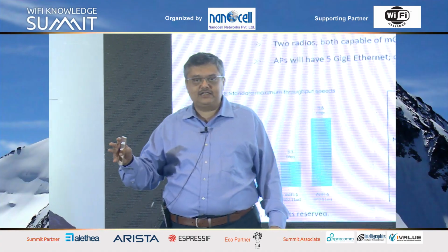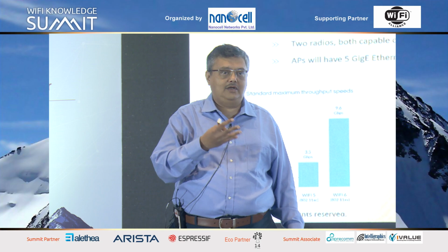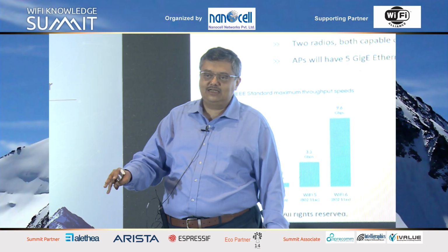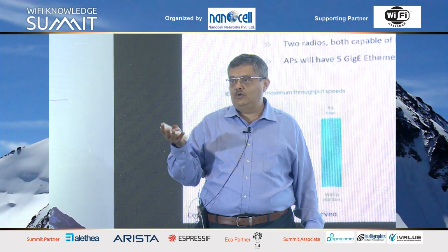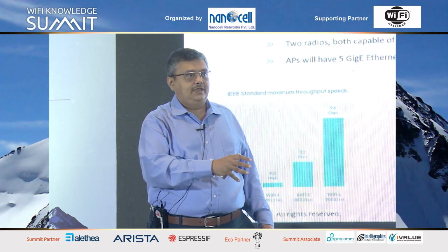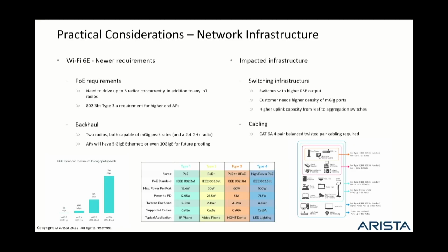A bulk of these access points are going to be an 802.3bt requirement, right? All of you probably know it's a 60-watt spec, which promises to deliver up to 53 watts to the PD. So basically you won't be able to live within the 25.5 watt budget that is provided to you by 802.3at. Now these switches are expensive.